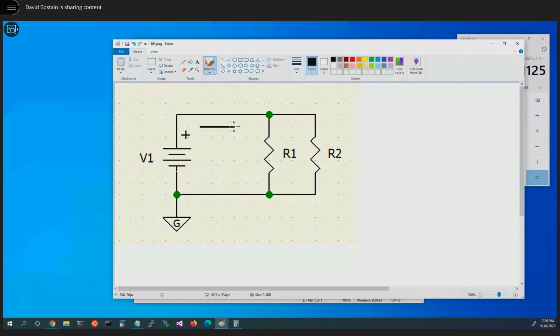that's coming into the circuit from the battery this direction has to go into this node and then split, and part of it go this way and part of it go this way. Then when it gets to this node, rejoin, and these two have equal value. How do they split? Well, they split proportionally to the values of these two resistors. These resistors are equal, we'll get half the current through each leg.